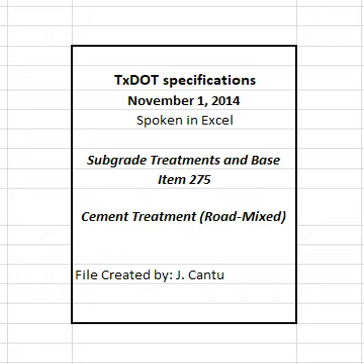The roller must travel at a speed of 2 miles per hour, vibrating at maximum amplitude, and make 2 to 4 passes with 100% coverage exclusive of the outside 1 foot of the surface grade, unless otherwise directed by the engineer. Additional passes may be required to achieve the desired crack pattern as directed. Notify the engineer 24 hours before the microcracking begins.